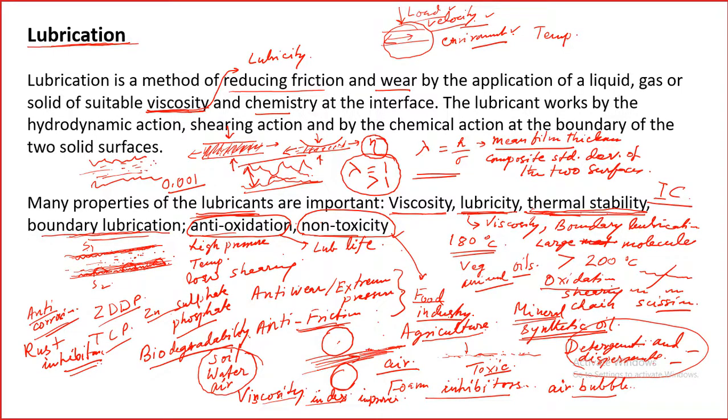There is one more thing which is called pour point depressant. So pour point is basically the temperature at which the liquid shows its flowing property. It flows. Okay. So pour point depressant is added for working in cold environment, because in cold environment the lubricant will freeze and therefore the lubricant will not work, at least in the beginning when you start the machine. So having lower pour point will help so that the lubricant remains in liquid state even at freezing temperatures, very, very low temperatures. So pour point depressants are added into the lubricant to help with this property.